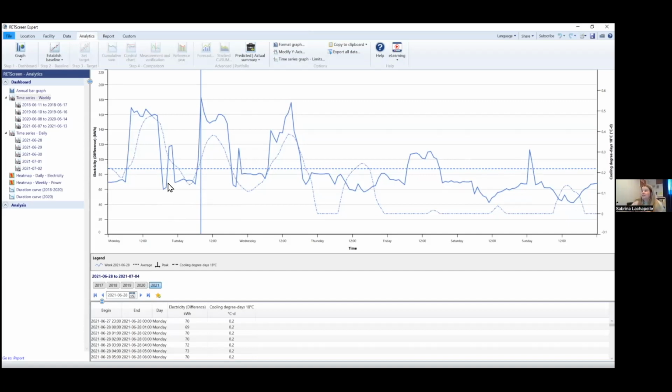have a control system that allows them to refill themselves starting at 9 in the evening up to 4 in the morning. So during the evening and the night, if the level of ice is too low, then they can produce a new ice. So the peaks that we are seeing here is when the ice banks are producing new ice.